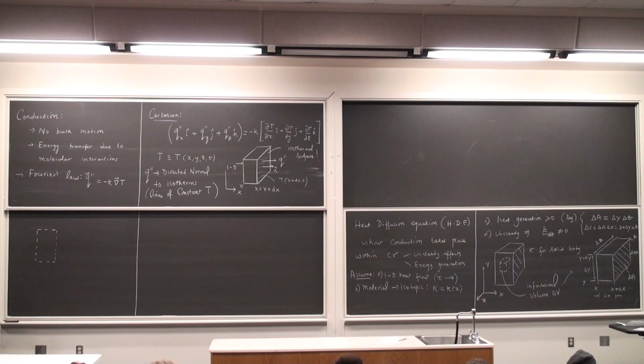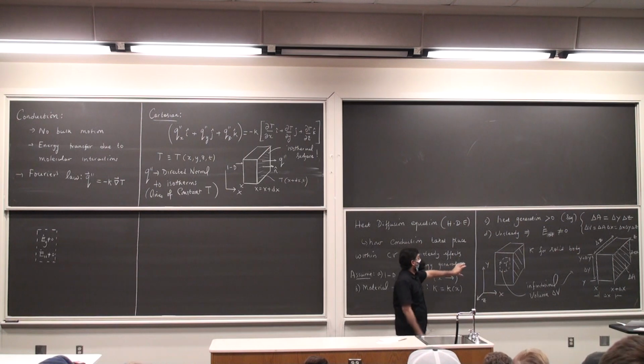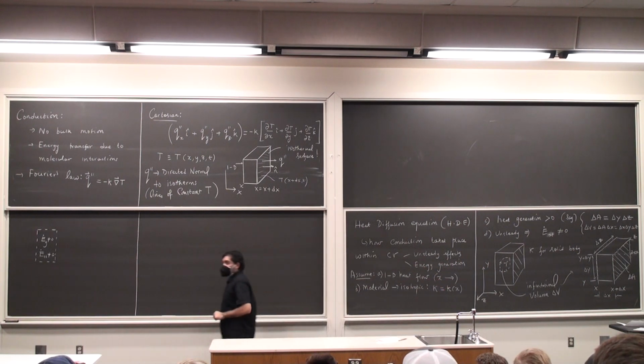There is heat generation within, so E dot G is not 0. It is unsteady, which means that there is variation of temperature with respect to time, so E dot stored is not 0. I want your help now. What is the variable that depicts the transfer of energy into the control surface here, on the left side, from the inner surface on the left? It has to be the conductive flux. Why is that? Why is there no mention of convection and radiation here? Because I'm taking this volume element from within the body. Okay, so keep that in mind, and thank you.